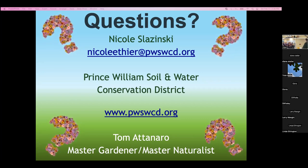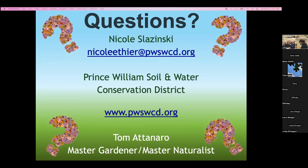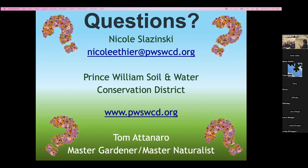What I've done in some situations, if the rain garden is too small, is find other ways to move the water. You can use swales, or other things that will spread the water over the rest of the yard and the rest of the garden. If you have lawn around your rain garden, that's a little bit harder, but if you have garden around it, it's easy to do. So I guess one solution is putting swales in and making the rain garden so that it will move the water to the other parts of the garden,